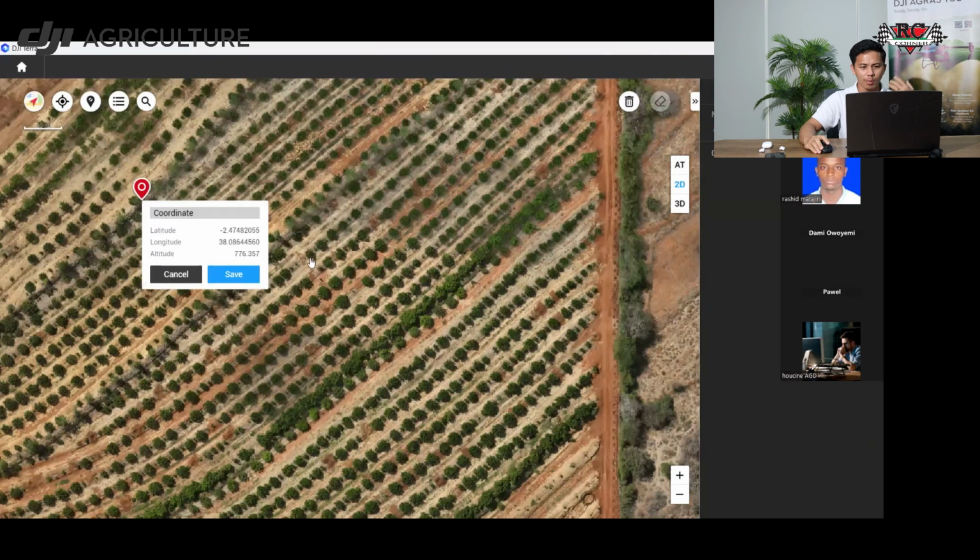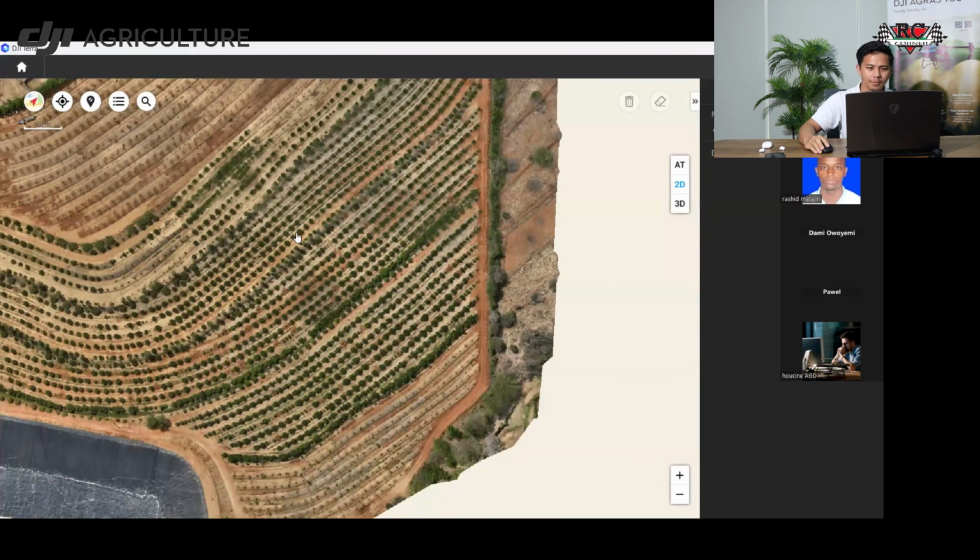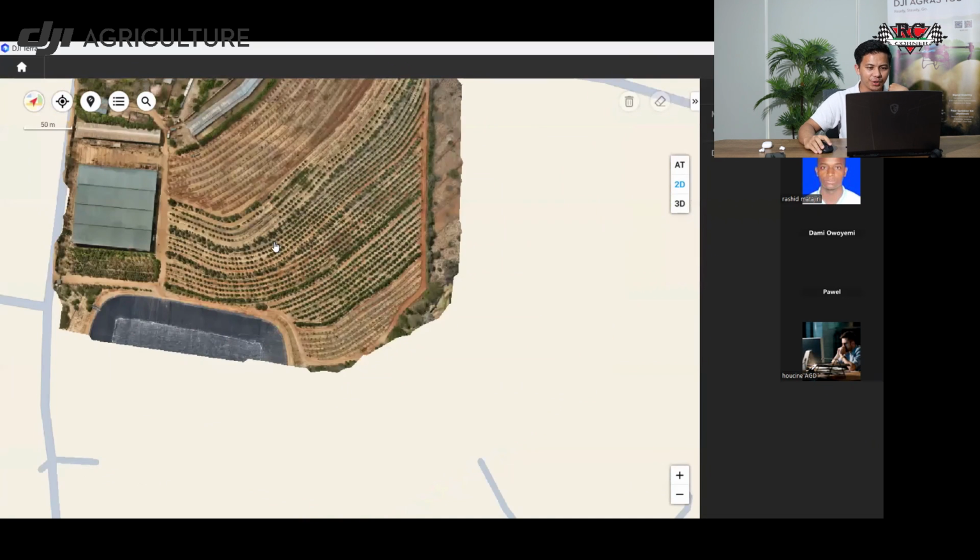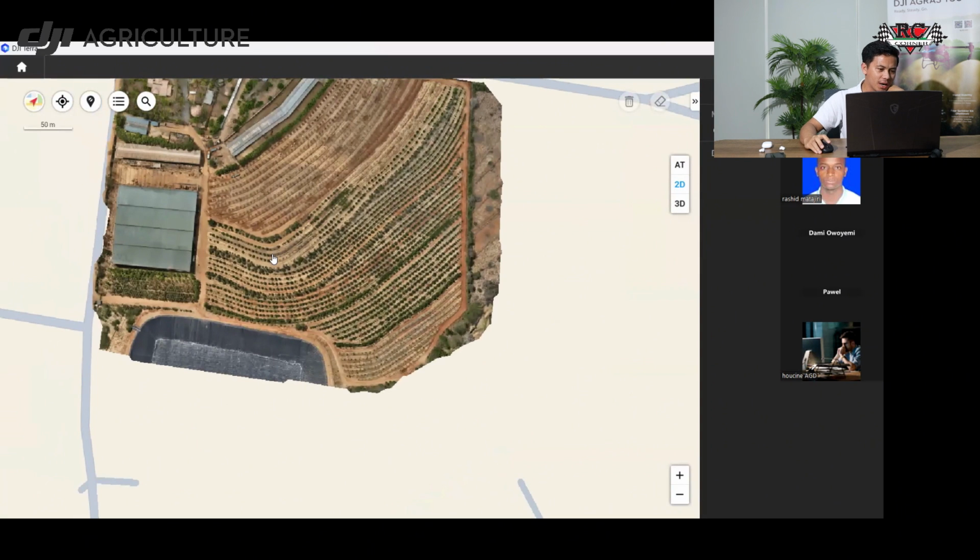The distance, I normally use the distance in areas. Why? I know from my VA experience, if you go for big trees like mango, durian, cocoa, coconut or date, I cannot see my drone. It is flying too far away. The drone limitation always says 1 kilometer, 2 kilometers, but in fact it's not flying that far in fruit trees because you cannot see the drone. If you maintain line of sight, yes, it is possible. But because of fruit trees, I cannot maintain the line of sight.